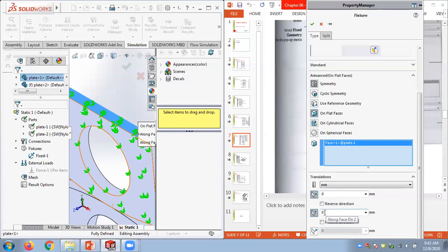If you give something like 1 millimeter here, the meaning is in x direction there can be 1 millimeter maximum displacement after applying the loads. But here if you say 0, there will be no displacement in x and z directions. But here I am not giving anything in y direction, so I am allowing y direction displacements to change. So this is how we give.